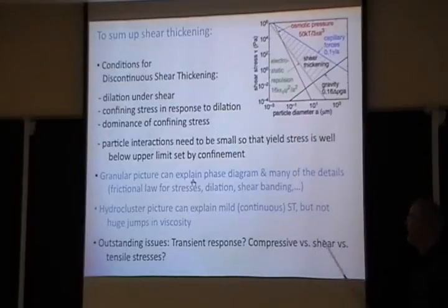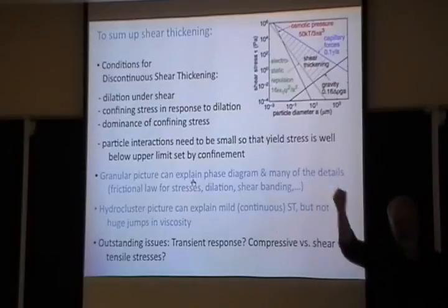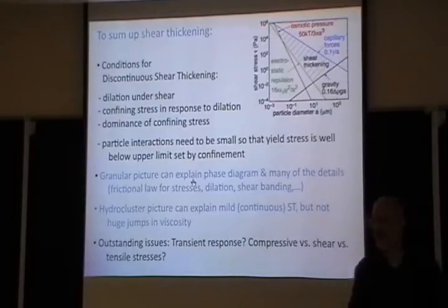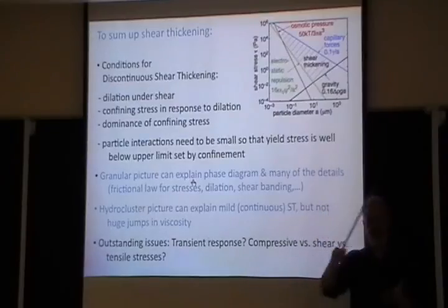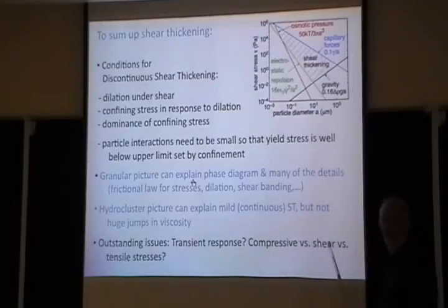In fact, we are doing compressive and extensional measurements right now. I saw some beautiful data, I guess you showed it, of an extending column of cornstarch, and it breaks apart, of course, like a solid if you do it faster, right? So the stresses under compression and under tensile loading are much, much larger than the stresses you get from shear.